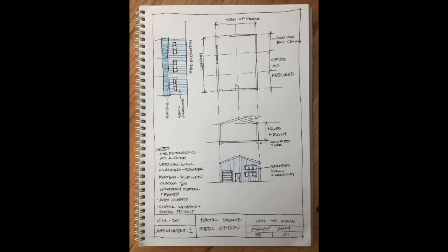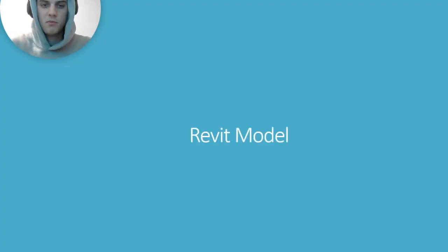The building length, frame span, and eave height specified are 20, 14, and 10 metres respectively, with the rafter load being 10 kilonewton meters. All concrete must have a compressive strength of 50 megapascals and all steel must be grade 300. Now we're onto our Revit model.